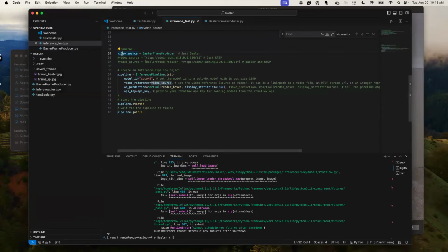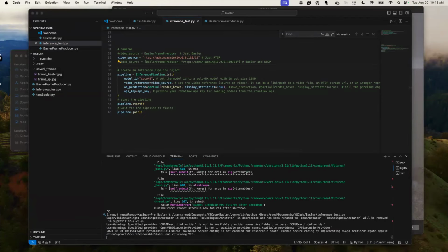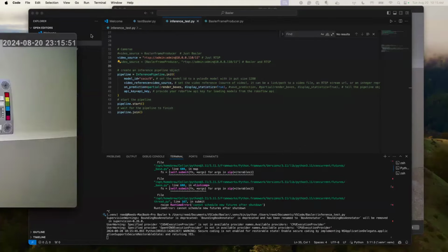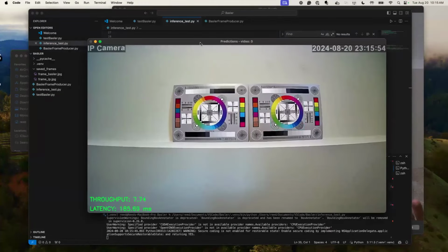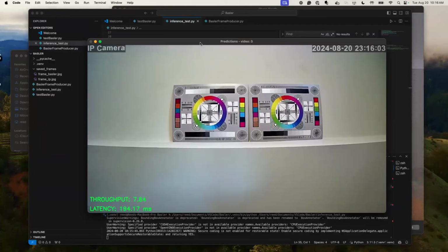Let's go look at the IP camera. This is the cheaper IP camera, and IP cameras are good for a lot of applications. If you just want to know the relative presence of an object, or maybe the color of the object, but you don't really care to pick out things like text on it, IP cameras can be good, and I'll show you why. Now you see this IP camera. It's got a wide field of view, and you can see both of these targets. The downside is I can't adjust the lens here. This is fixed, so this is what it's going to have to be, but it's much cheaper. The resolution is okay. We're getting some weird warping on these numbers and all of that. But that is the IP camera.